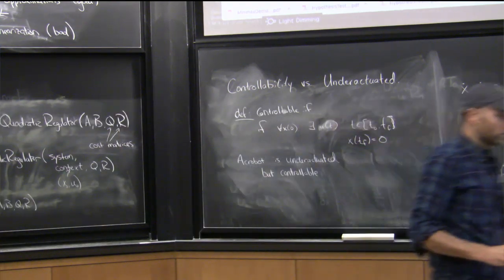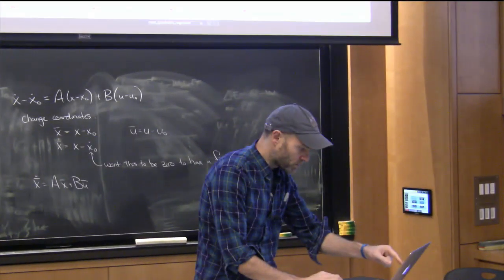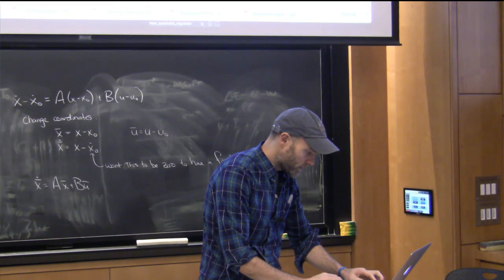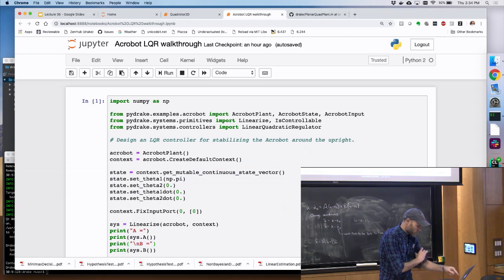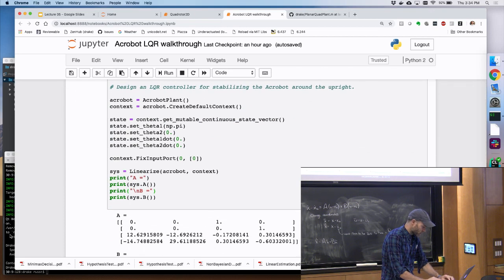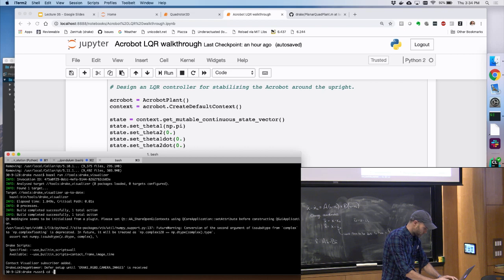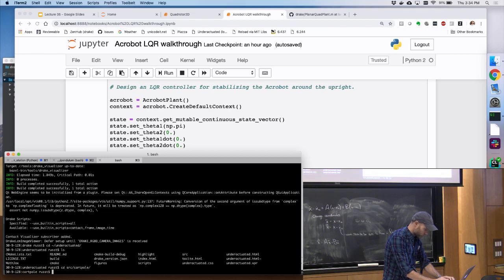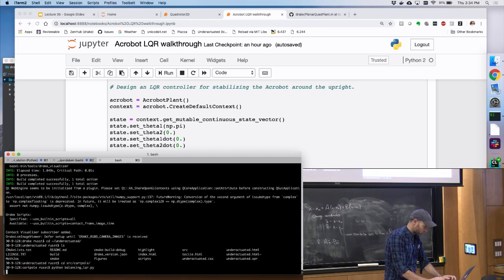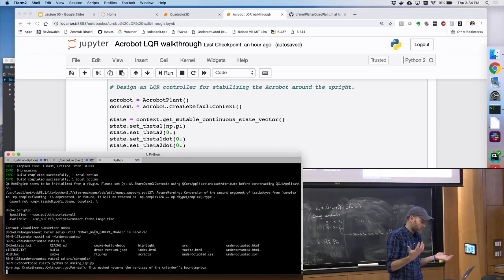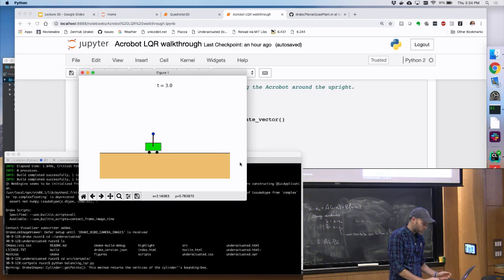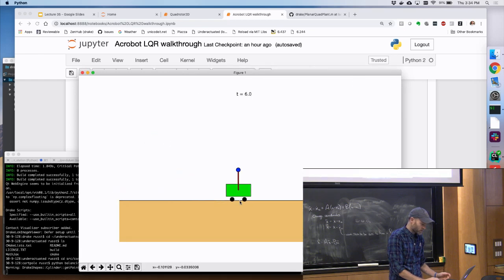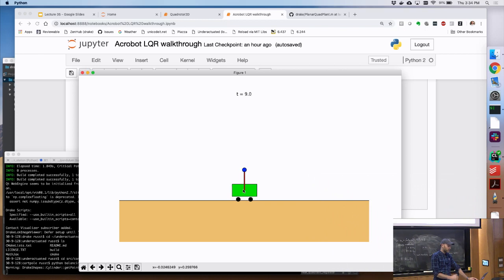Okay, so let me show you that this stuff really works. I wanted to plot out in this window that it's easy to write the code. But then if we actually go and run the code here, I'll do the cart-pole first, exactly the same math works. I'm stabilizing the origin, which is somewhere around here, and I'm going to give it a push every 10 seconds or whatever it is, and it's going to try to recover.